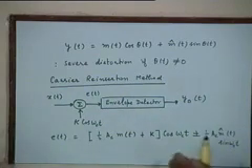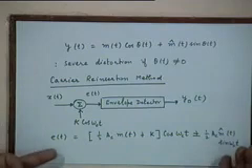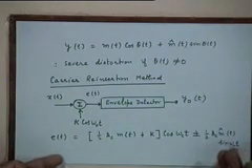So this falls in the general class. This is in conformity with our discussion on the general representation of bandpass signals, which has an in-phase part and a quadrature phase part. Only thing is that there is a special relationship between the in-phase and quadrature phase parts for it to become an SSB signal, right? That we have understood now.